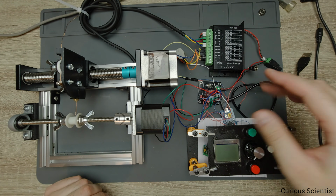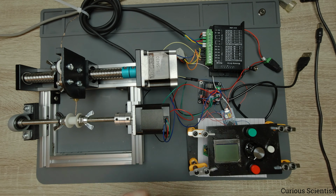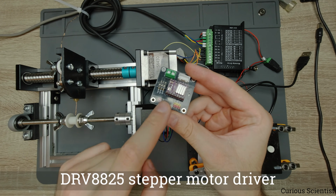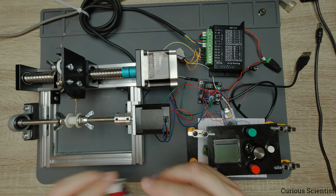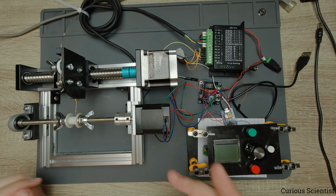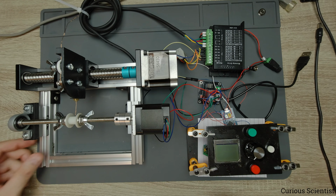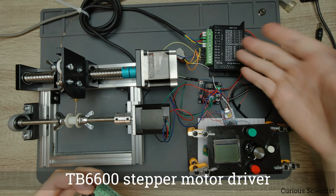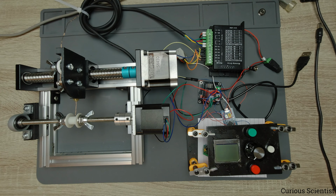And then regarding the electronics, as you can see, now we have a different stepper motor driver, because this was previously a NEMA 17 stepper motor, so it was enough to use this DRV8825 stepper motor driver. But now, since I have a larger motor which can run at higher currents, of course we do not necessarily want to run it at high currents, but why not? I just have this TB6600 stepper motor driver. It works with the same principle as the other, but it provides more current.